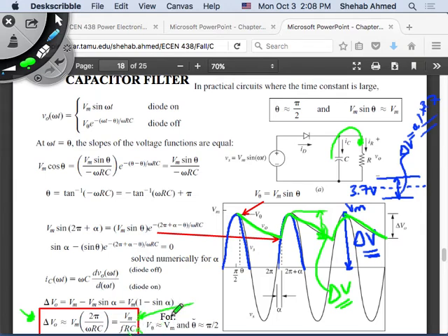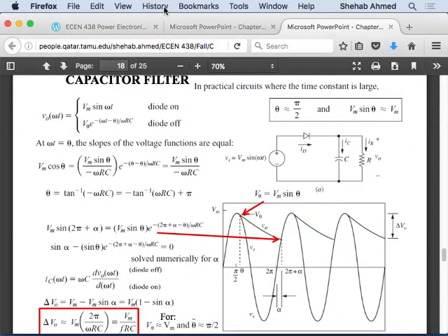What's another? So now we see C and we see R. How about F? If I increase frequency, I decrease ripple automatically. Why is that? Exactly. Right? So they will be closer. So for the same value of R and C, remember, what's happening as soon as the diode disconnects? Then this capacitor is discharging to the resistor, right?